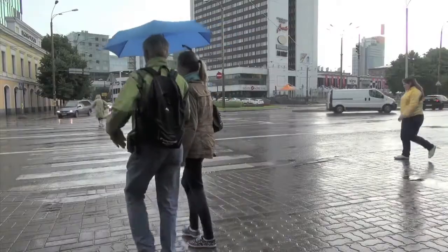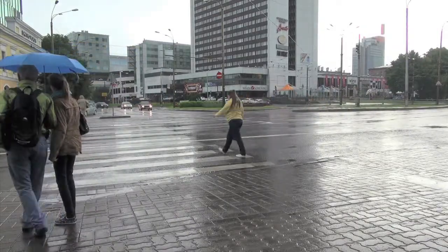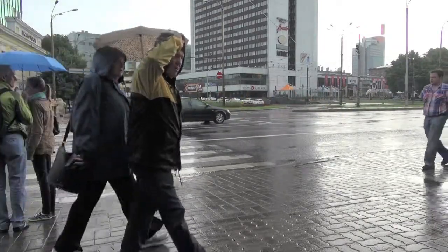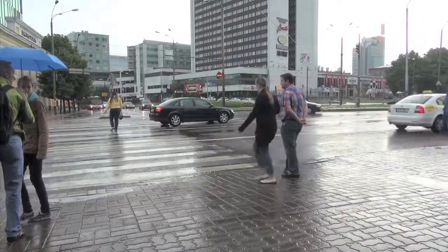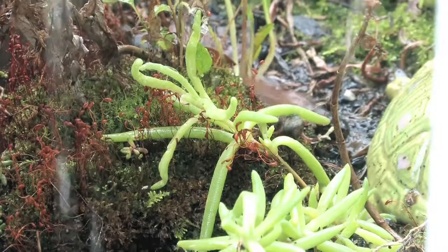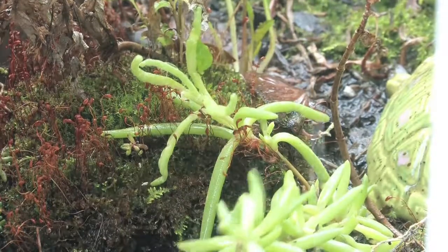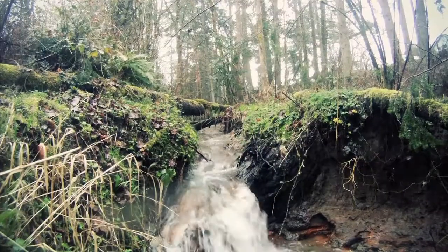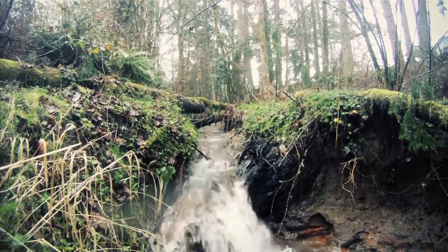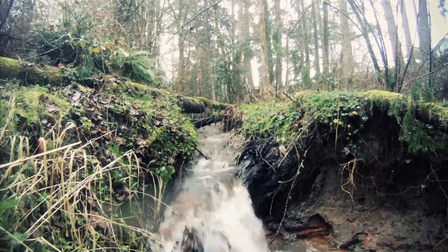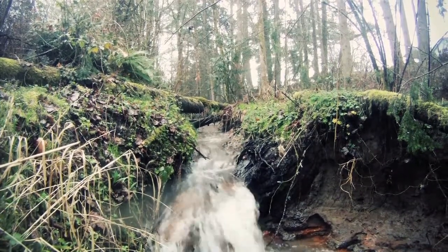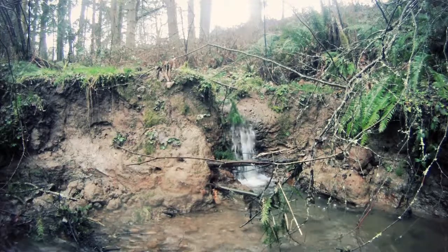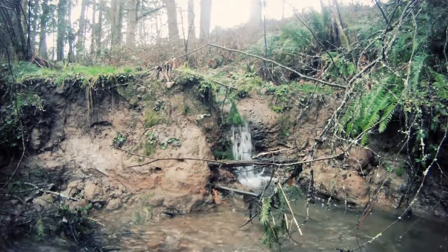Again, traditional development practices cover large areas of the ground with impervious surfaces like roads, parking lots, and buildings. Under developed conditions, runoff occurs even during small precipitation events, when that precipitation would normally be absorbed by the soil and vegetation. The collective force of the increased runoff scours stream beds, erodes stream banks, and causes large quantities of sediment and other entrained pollutants to enter the water body each time it rains.